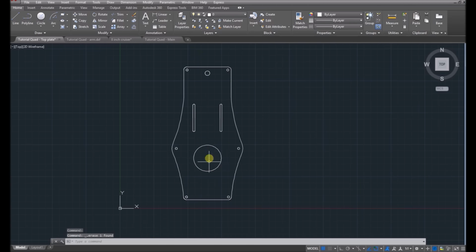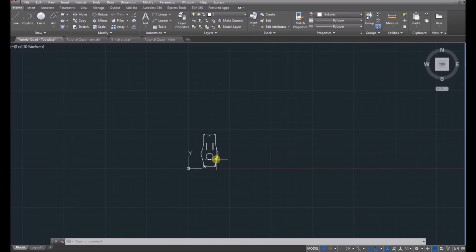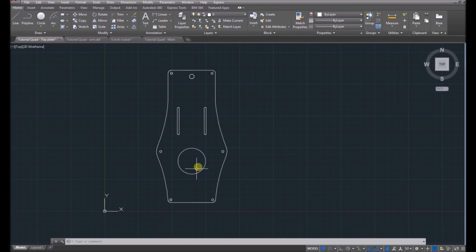And I kind of like doing that in my ZMR Slim frame. I did something like that because then you can have your XT60 battery lead coming out this big hole here, and you've got your battery here, and that way your props are well away from the XT60 lead. There's no way it can be cut because it's going through this big hole in the middle. So that's why I'm a big fan of big holes in the middle of the top plate.